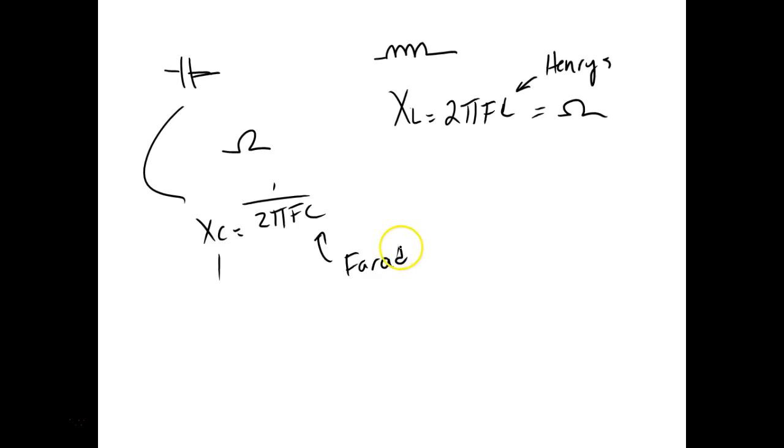Because the problem is its opposition changes with what? Frequency. So as frequency goes up, a capacitor's opposition goes down. And if frequency goes down, the opposition of the capacitor goes up. This is why if I use DC, it has infinite resistance. That's why when you take an ohm meter and measure it, because your ohm meter puts out DC, it measures infinity, because you have no frequency, right? You understand? I take that same capacitor and put it across 100 hertz, and then it's going to let information flow. It's going to let things flow through.